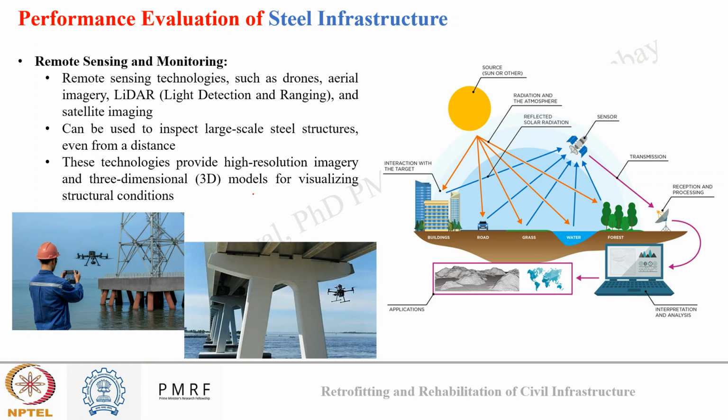Also, drones are used to inspect areas like some jetty structure in between oceans where it is difficult for an engineer to reach and inspect, or for structures below a bridge deck, the steel columns, if there are some steel columns there also, we can use drone to capture high visual images to inspect the structure. In the adjacent figure also you can see one example where a sensor drone was used to inspect a building.